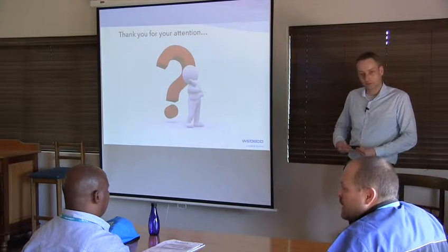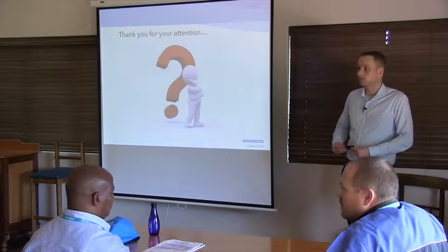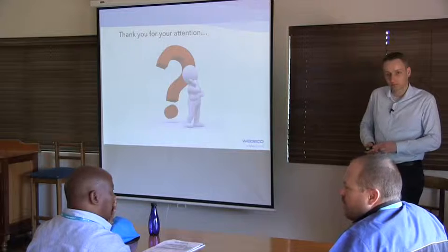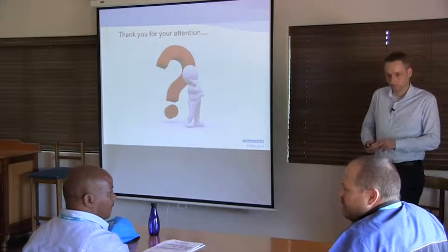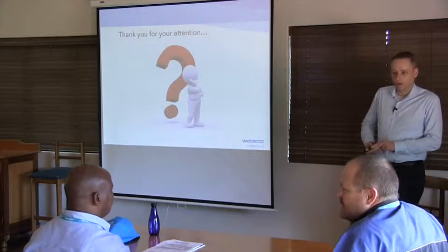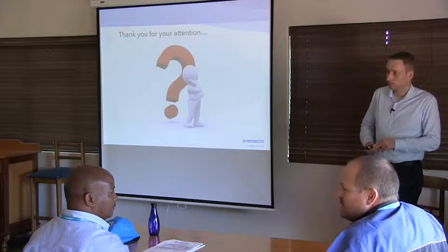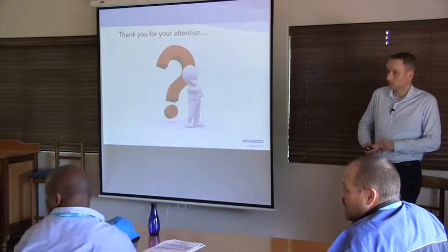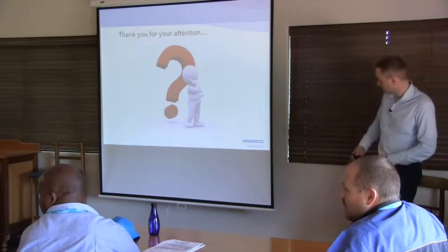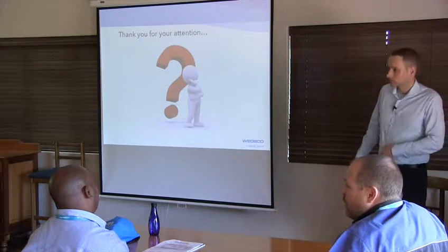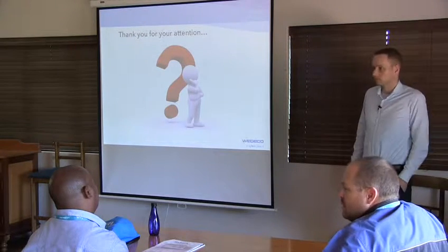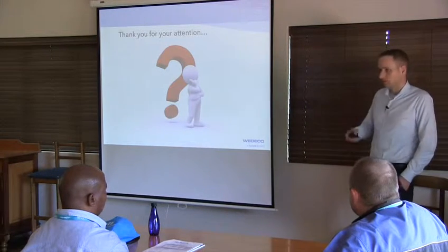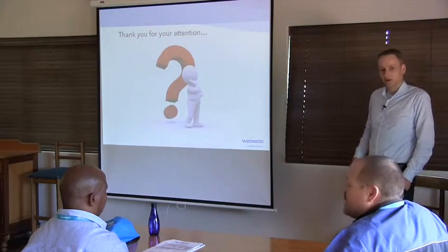Do you have systems that automatically switch themselves off? Yes, you have a no-flow valve, like you do for UV disinfection in a home. You don't want problems. At maximum range, you get a solenoid valve. If something happens to the lamp or whatever, it should switch the lamp off automatically. We have over-temperature switches. It's just basically a bimetallic plate, but that doesn't come standard.